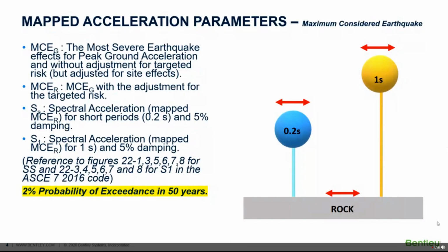You can see that the spectral acceleration is constant between the periods T0 and Ts. Ts is calculated as the ratio of SD1 to SDS, while T0 is 0.2 of that ratio. Now, if you think carefully, with softer and softer soils, the T0 and Ts would be shifting right, and so would the flat portion of the design spectrum curve, which represents the highest spectral acceleration. This is the acceleration domain of the response spectrum curve. The spectral acceleration in this region would be equal to SDS.